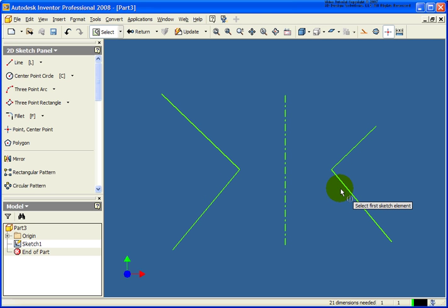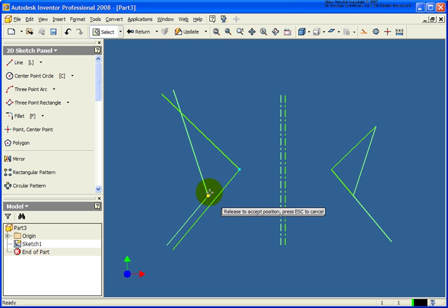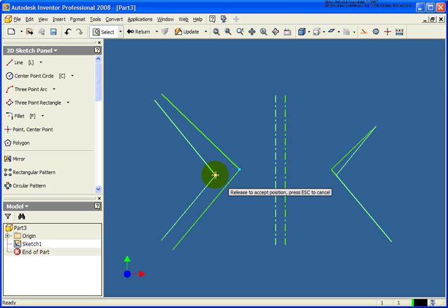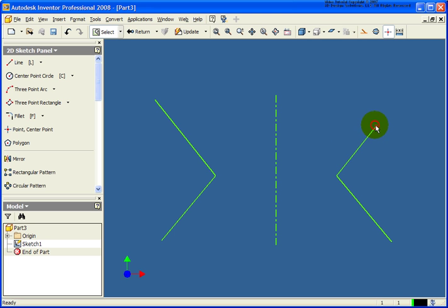While I'm still in that tool, I no longer had to select the center line since it already realized that it was. Now if I stretch this out, you'll see that the angles are exactly the same. Of course, in this case, the size is not, so I can maybe apply an equal constraint to give the size on both lines exactly the same. So the symmetric constraint is allowing me to define the angle for each of those line segments.